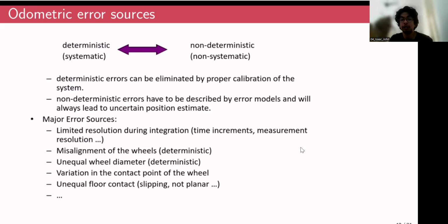Right? We cannot have continuous sampling. It only samples in discrete times. So that is one major error source, because of the discreteness or discrete sampling. Any features that come between these two samples will have to be interpolated, or will be completely missed. So we won't be able to get the exact dynamics between two sampling points, and there is no way to completely eliminate this sampling time. It's always going to be discrete. So that is one major error source.